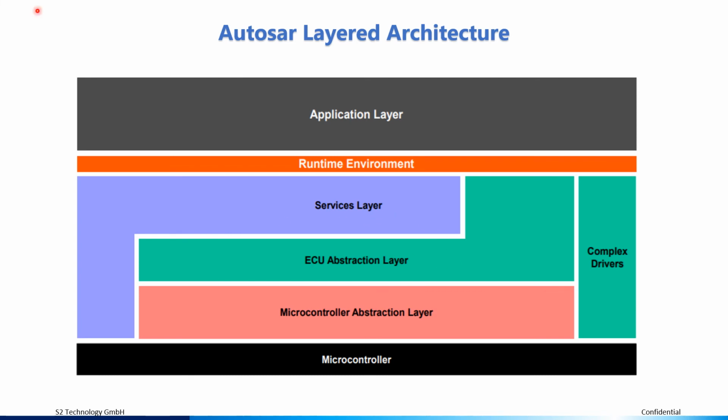Then we have the services layer, where the service offers the functionality of operating system functionality, vehicle networking, memory services, diagnostic services, ECU state management, logical and temporal program flow monitoring, cryptographic services and many more.